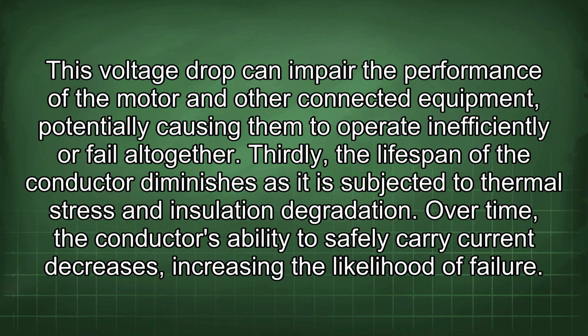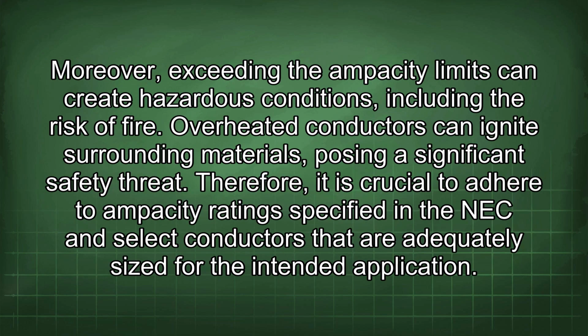Secondly, voltage drop becomes more pronounced as the current increases. This voltage drop can impair the performance of the motor and other connected equipment, potentially causing them to operate inefficiently or fail altogether. Thirdly, the lifespan of the conductor diminishes as it is subjected to thermal stress and insulation degradation. Over time, the conductor's ability to safely carry current decreases, increasing the likelihood of failure. Moreover, exceeding the ampacity limits can create hazardous conditions, including the risk of fire. Overheated conductors can ignite surrounding materials, posing a significant safety threat.